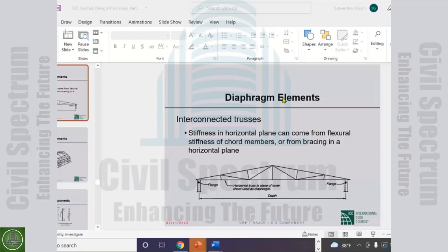Shears are very high. It's several thousand kips at the bottom of those towers, and that all has to go through the slab. So the basic answer to your question is no. We don't have to rely only on concrete to carry shear. If we are prepared to provide reinforcement, that's allowed.